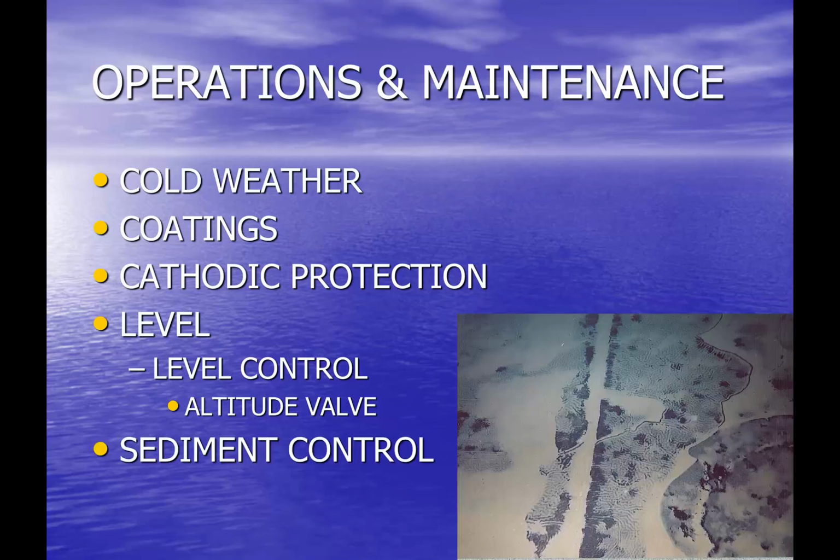One of the other things to pay attention to in reservoirs is that we can accumulate sediment on the floors. It is something that can be a water quality problem, especially if you are taking water down relatively low or draining the reservoir to a significant extent. This kind of thing can be cleaned up during maintenance activities. It's also something that literally can be vacuumed up by divers, which is something that we've successfully done occasionally, depending on the nature and magnitude of the problem.